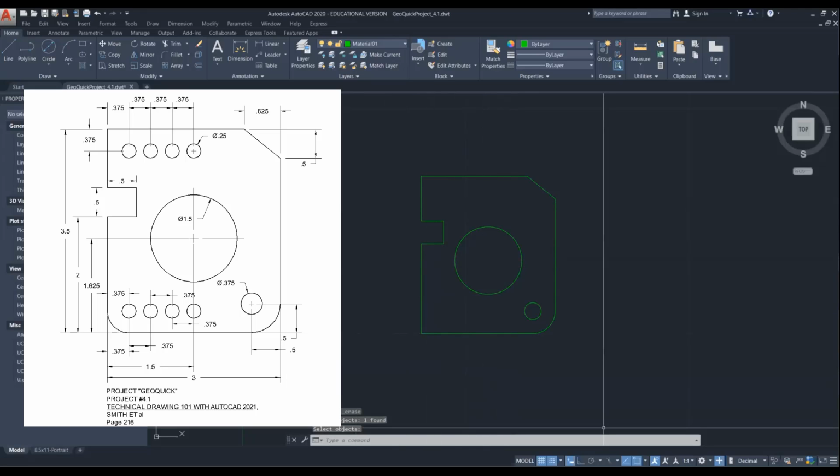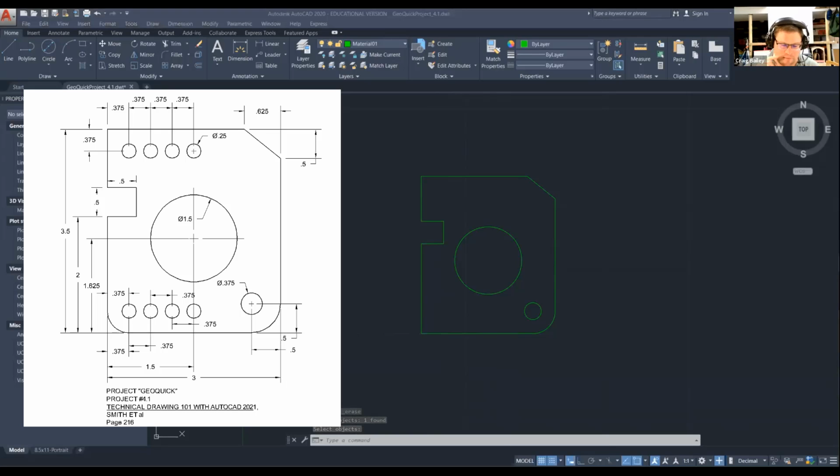Back in here. So before you do this circle, I think there's one thing that you're missing. Can you guess what I'm going to say? No. The location of that first circle is concentric to the fillet radius. I would start with the fillet radius.